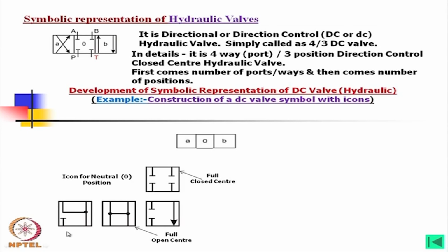Definitely if the pump is closed, that means the delivery side is closed, it will develop a pressure beyond the pressure we are utilizing for the system, and then this oil has to go through the pressure relief valve.